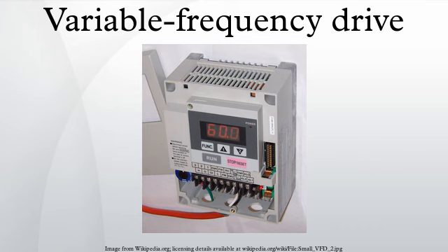Note of clarification. While harmonics in the PWM output can easily be filtered by carrier frequency-related filter inductance to supply near-sinusoidal currents to the motor load, the VFD's diode bridge rectifier converts AC line voltage to DC voltage output by superimposing nonlinear half-phase current pulses, thus creating harmonic current distortion, and hence voltage distortion, of the AC line input.